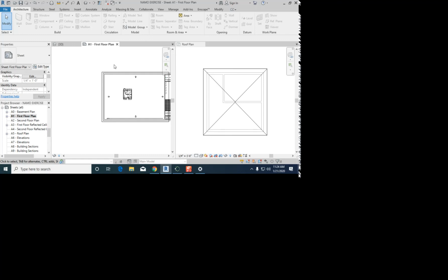We're also thinking about the constraints, and that's the finished face exterior or interior. Even though we can draw center line, is that what we use in this class often? Typically not. Sometimes if we have a big house and we want to draw 3 bedrooms or 3 offices of equal size, we'll draw them in the center and then we'll equal them out. But typically it's finished face interior. Sometimes it's finished face exterior. Good. And then you guys mentioned the template too, whether we want to do architectural or residential.